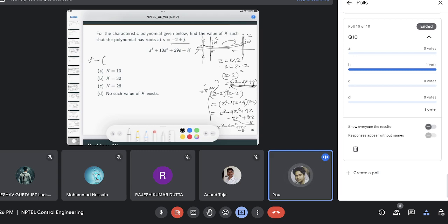The summation of all poles, if there are n poles, since the order is n, minus 1 plus the summation over i and j of pi pj, taking two poles at a time, then minus, plus, continuing, minus 1 to the power n, then you take all the poles and multiply them, the product of pi from i equal to 1 to n.